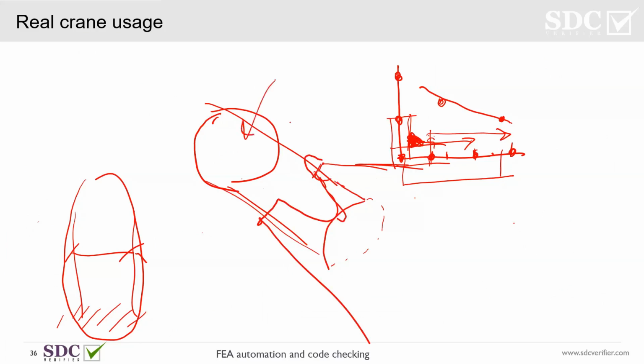So if you have the pipe like this, maybe that's not the perfect drawing, and here you have a gusset plate. Sometimes they add an extra plate which provides stress relief at the ends, basically for this stress concentration location. That is also often used as a reinforcement. So if you have this kind of connection, you have to model that in detail as well.